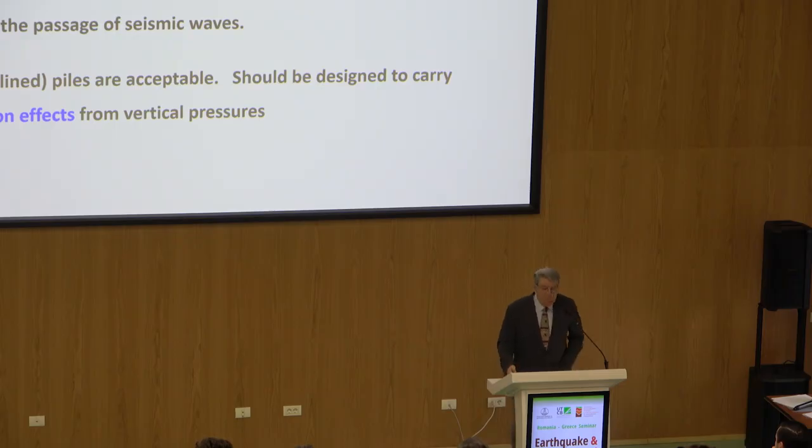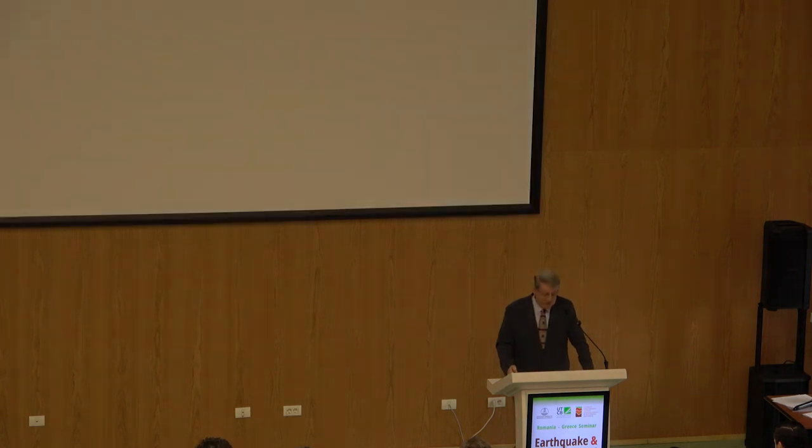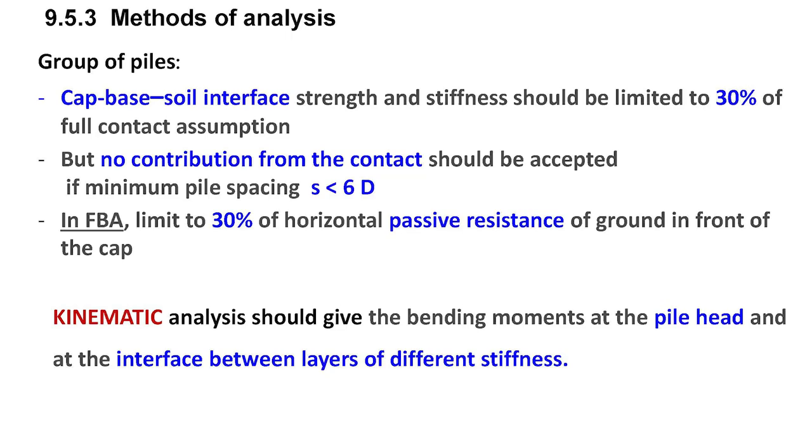Battered piles. And why do you say they are inclined piles? In previous codes, they were very strict, they were forbidding actual battered piles for whatever reason, because they thought the axial forces are very significant and they will create buckling. Now we have abolished this idea, but still battered piles should account for the additional loading from the gravity, in addition to what comes from seismic action.